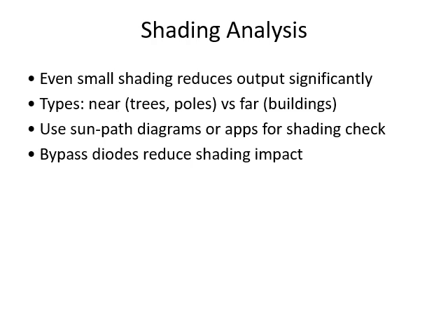Since all these photovoltaic cells are in series and one is not generating current, it is supposed to break the circuit, right? But if you have the bypass diode connected in parallel to all these photovoltaic cells, then it will bypass the non-active solar cell. Okay, and then it will allow the current to bypass the shaded cell and it will come to the main supply.